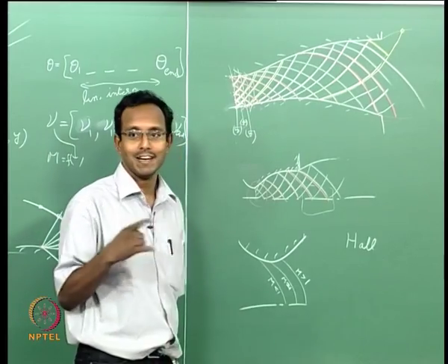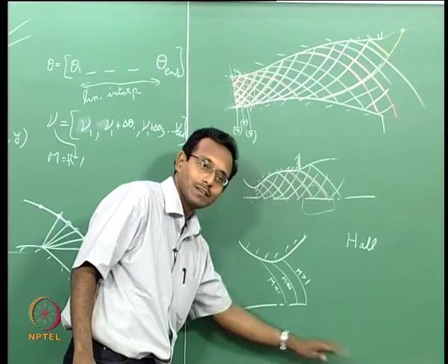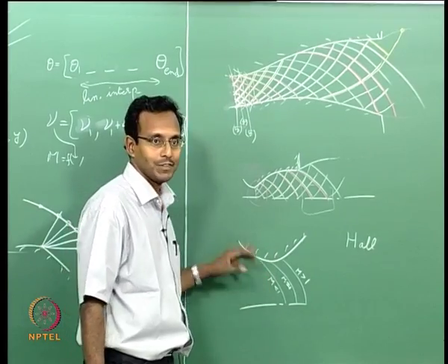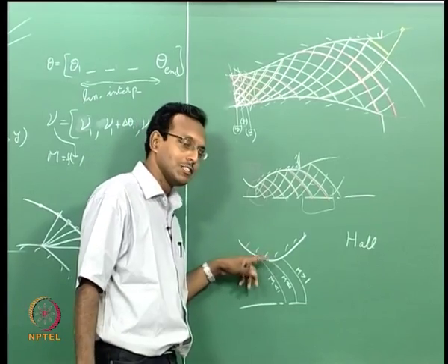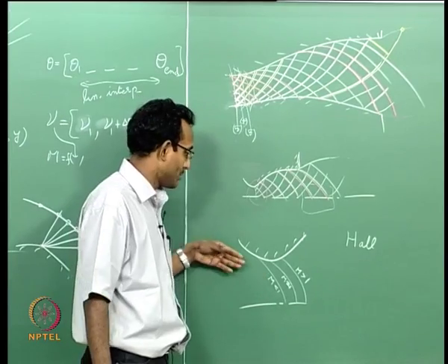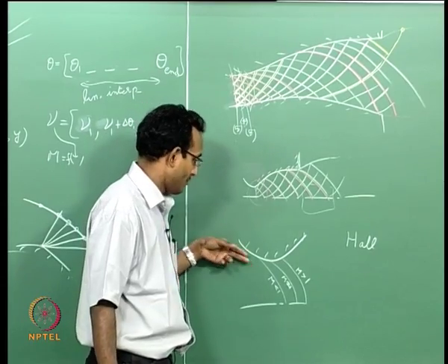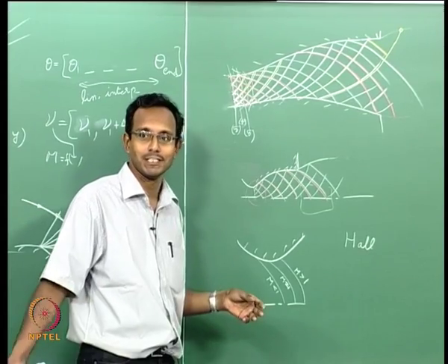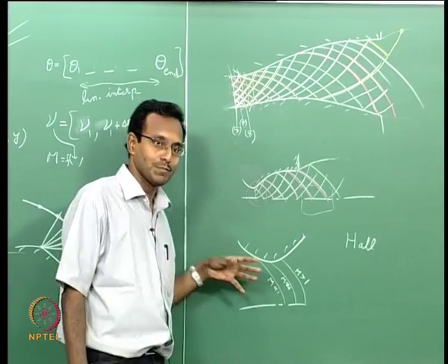Completely analytical work. What they really did was they imagined one cylinder this way, another cylinder this way, flow in between two cylinders, choked flow in between two cylinders. That is the problem they solved for. They have given analytical expressions for velocity, actually they have solved for u and v. So from there we can get theta and M if we want. It is not simple, they have done some series expansion based mathematical methods to solve for this region. The solutions are published already on the web.